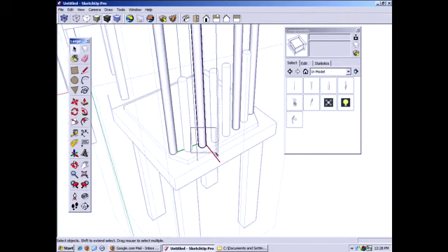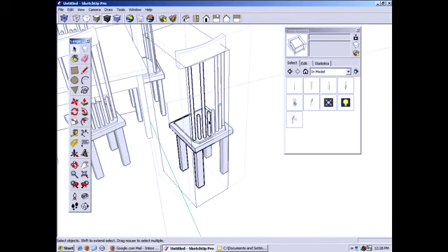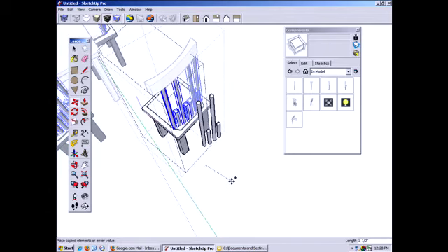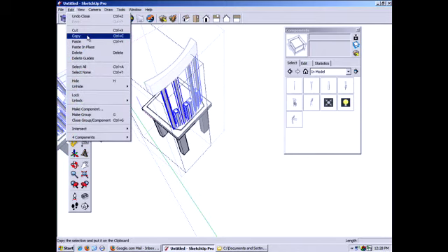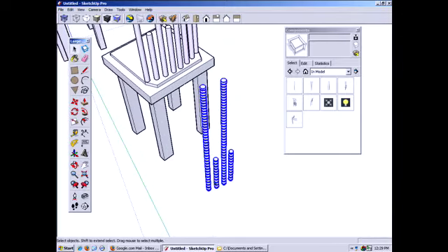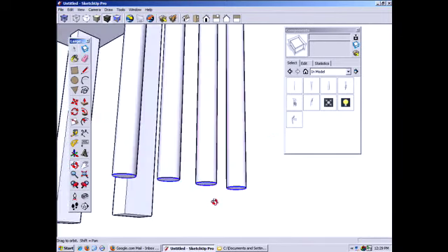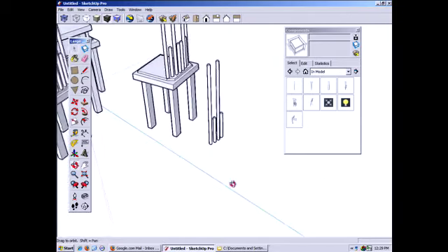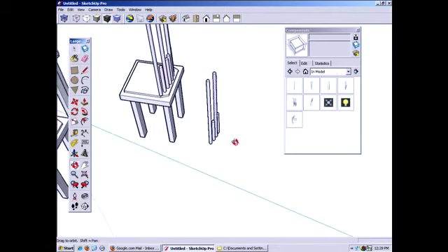I'll just come in to, say, this component. Actually, what I'll do is take these 4 components, and I'm going to copy them. Copy them, and then I'm going to paste them out here, explode them, which I did with keyboard shortcut, and just select the bottoms. Copy those. And if I was smart, I would have done it in the same place, so I would have had the advantage of paste in place.